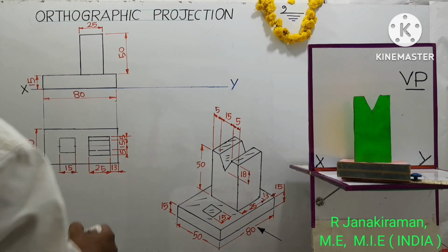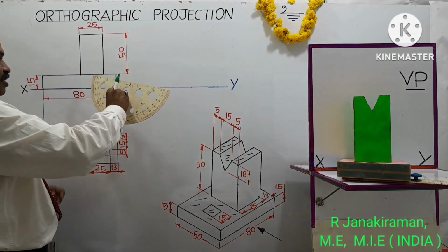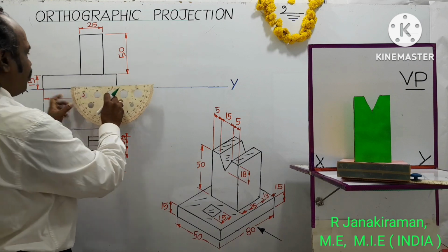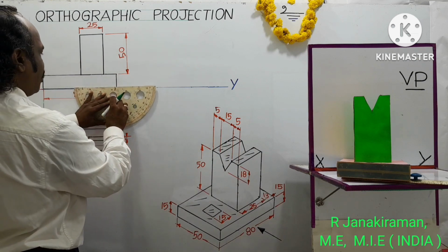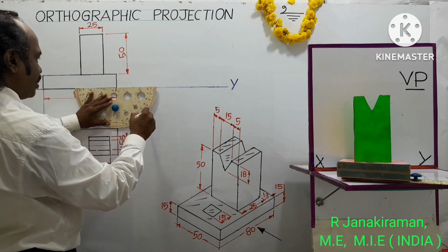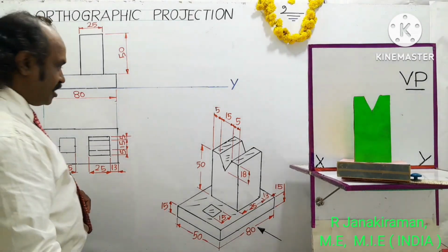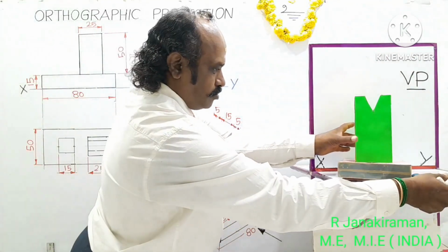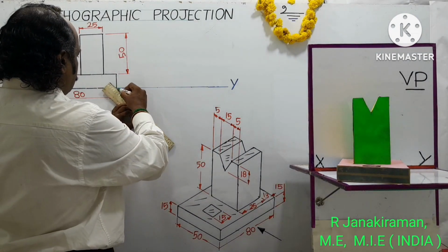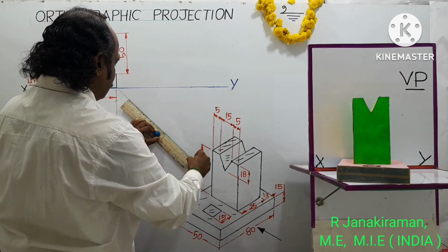It shall be drawn on the right side of the front view. So take your protractor, turn your protractor, keep this end point of the front view as reference. Draw one 45-degree inclined line, called the miter line. Read like 0, 10, 20, up to 45, and mark a point at 45 degrees. Draw through the marked point by freehand scale. This type of line is called the miter line, drawn by a 2H pencil. It's a lighter line.